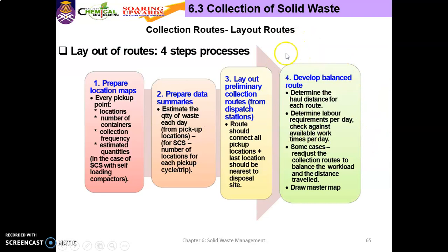And four-step processes. Okay, first one is prepare location maps, prepare data summaries, lay out preliminary collection routes, and lastly, develop balanced routes.